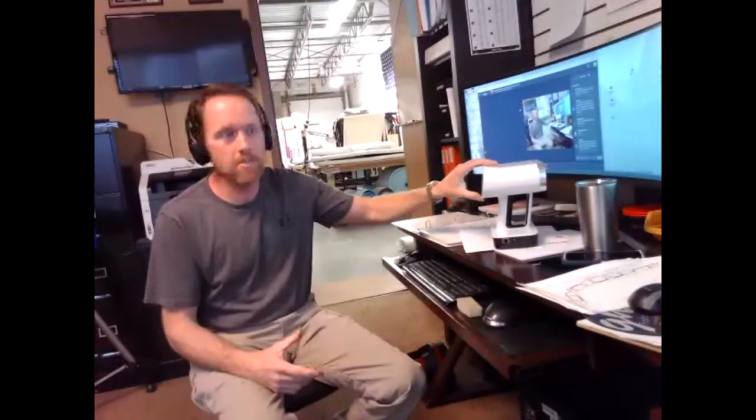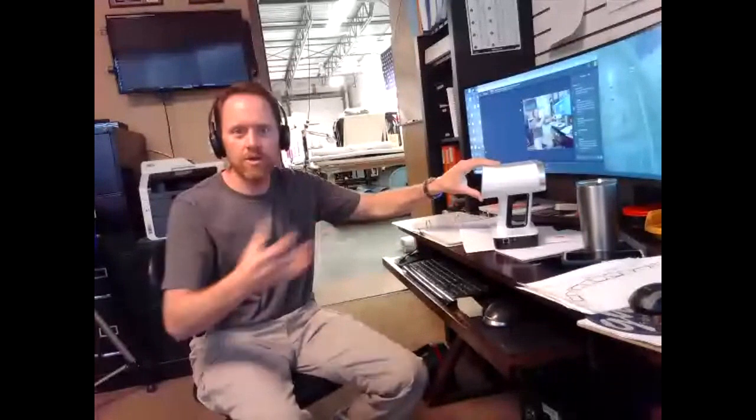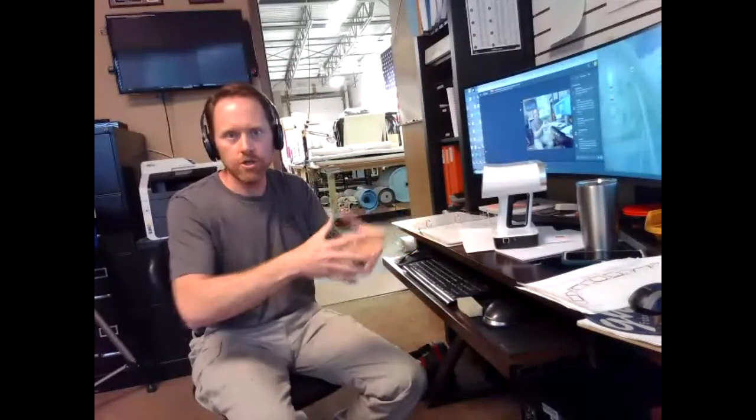It actually scans into a mesh, which is very easy to work with in Rhino. So imagine scanning a seat or a console cover or a pedestal in a boat, something small that we all have worked with. You could scan that pedestal. Now it's like working digitally with that real live pedestal. You would draw a framework over top of it, showing where your seam lines are, and then you surface it. If you surface it, everything should be inside that surface, and your cover's good. You just have to break it out into your structure before you surface it, so you're getting the right shape. But quite easy to work with.